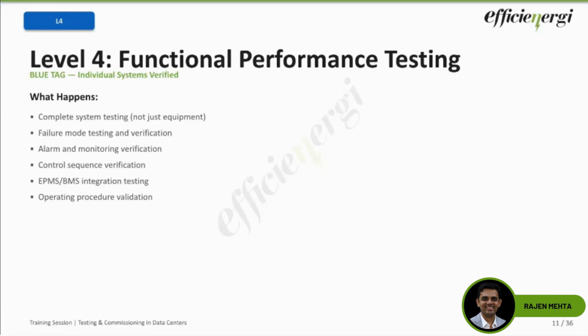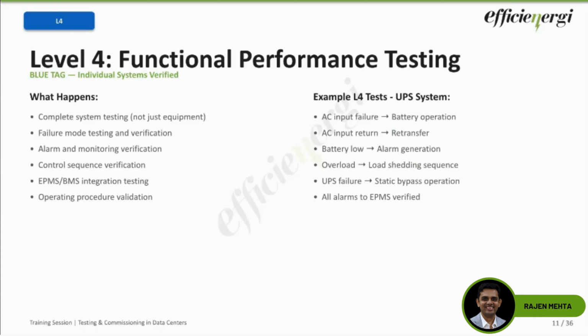For example, take a UPS, L4 test for UPS, you will simulate the utility failure, right? AC input failure will be simulated. At that time, the UPS should transfer to the battery seamlessly. Most important. Second, you simulate the AC input return, that is you simulate the utility return. The UPS should retransfer correctly.